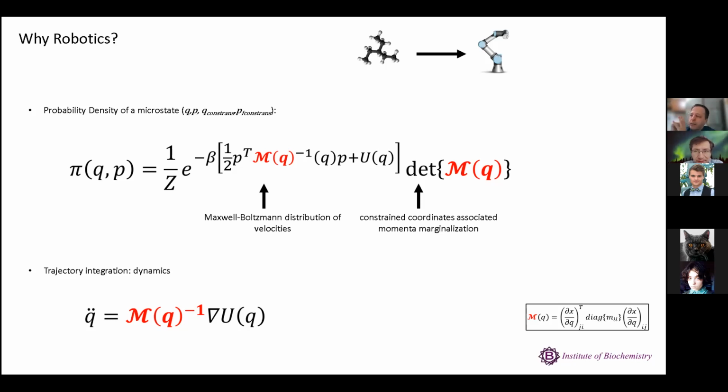It has a special structure because it embeds all the information about how the bodies are linked. So once you know how the bodies are linked and all the vectors and what degrees of freedom they have, and you know the masses and the inertias that they have, you can deduce an algorithm that can do this recursively.